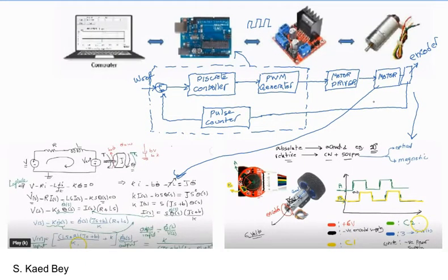If you need to do a more detailed analysis in MATLAB for the motor in, for example, open loop or closed loop configurations, you need the mathematical model for the motor together with that of the H bridge. I will show you how to do this experimentally later in the video. But for now, it's very important to find the number of pulses per revolution, as this will help us calculate the motor angular speed in Arduino. We have to use that information as feedback to the Arduino.